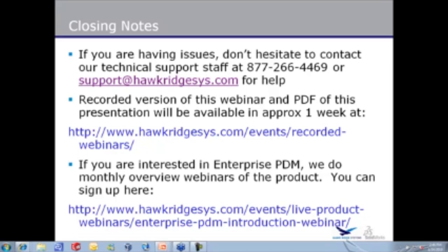Should the service pack for PDMWorks Workgroup be the same as the service pack for SOLIDWORKS? Yes. It does not have to be the same, but in order to get the best performance possible, it really should be the same. Is there a report that can tell me if a project has more than 2,000 files? Yeah, there is, Patrick. You just click on the project, right-click on the project and choose to run a report, and it will let you know how many files specifically are in that project.